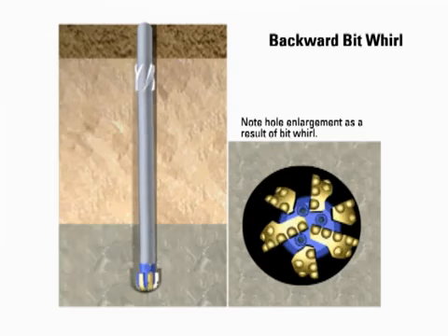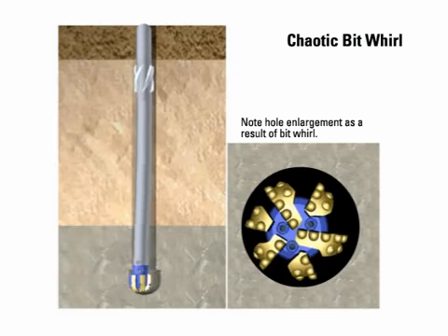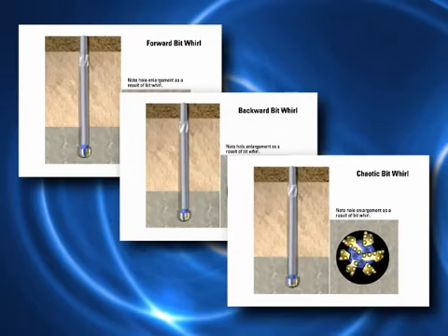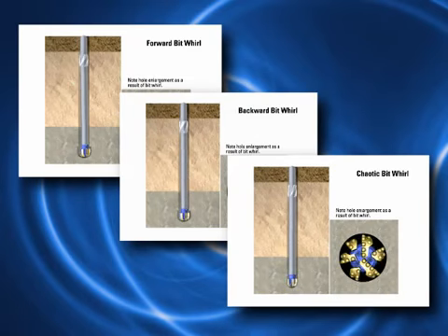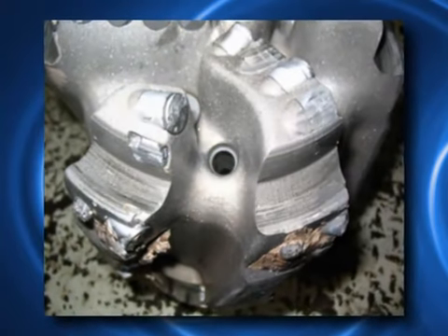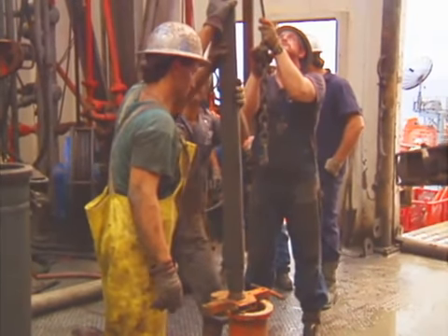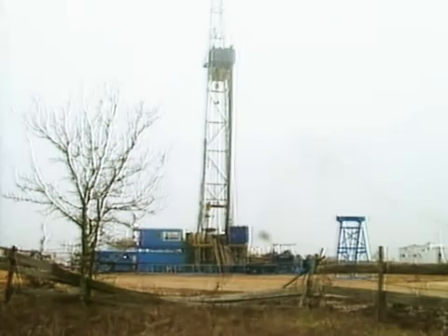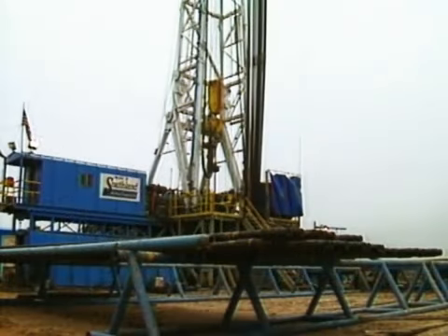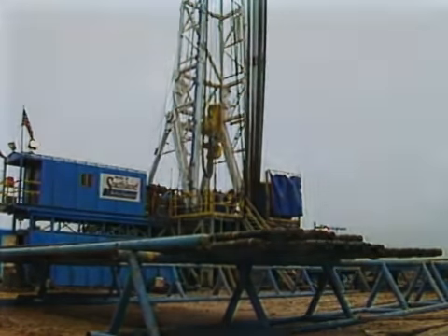It is caused by non-symmetric cutting action of a real formation that displaces the bit from its center of rotation and then allows the bit to move. Verification of shock and vibration can often be obtained by examining the bit after a trip. When dealing with BHA whirl, it is sometimes necessary to stop drilling completely to cure it, depending on the severity of the shocks and difficulties with drilling.